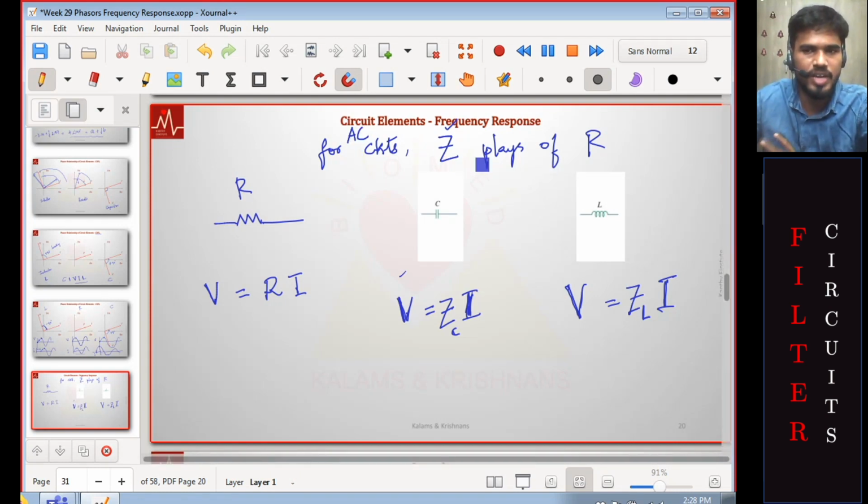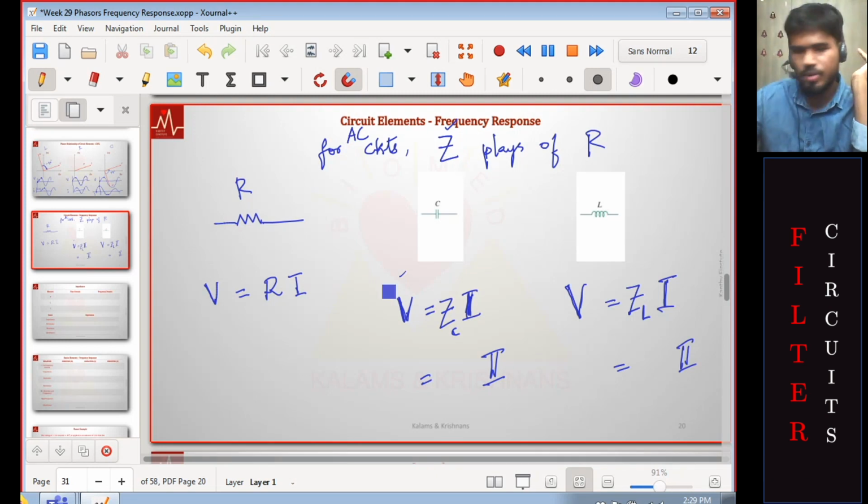And specifically this complex number, again, the math is given in the recorded videos. ZC, what is ZC? Can we be slightly specific about this complex number? If the capacitance is C, what is this complex number? Again, if I write it down, you might start recognizing it. Take the capacitance, 1 over that with a j omega term. So notice this impedance depends on frequency, is a complex number, so there is the j over there. C is a constant capacitance.